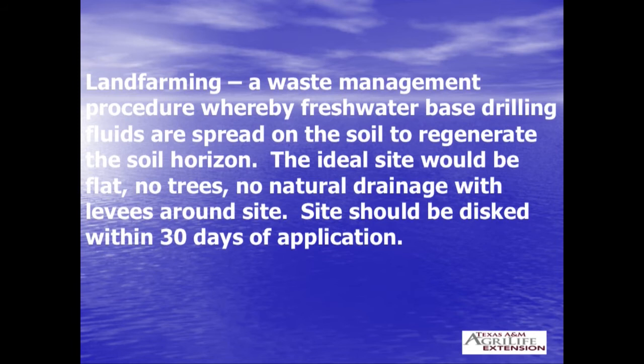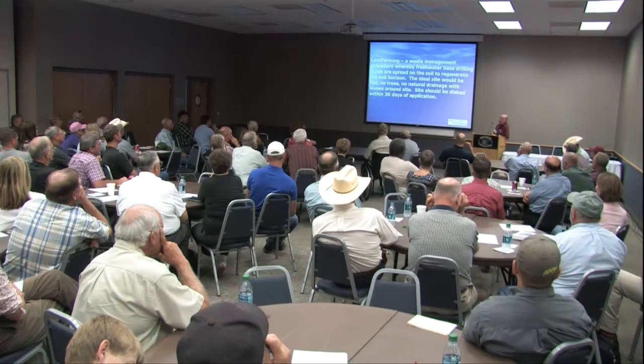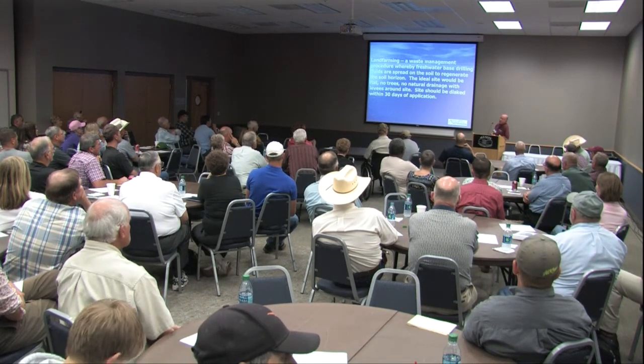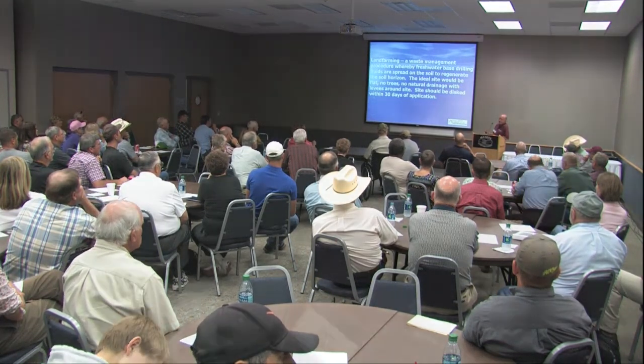The ideal site would be flat, no trees, no natural drainage, with levees around the site. Site should be disked within 30 days of application. Okay, got a few things that I don't agree with on that one. Number one, it is not a regeneration of the soil. This material can be detrimental if it's not applied at the proper rates, and so it does not regenerate soil.